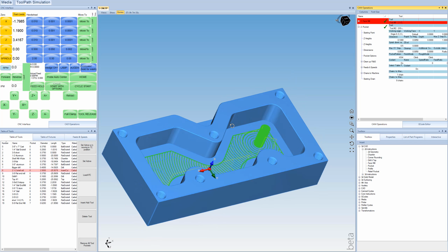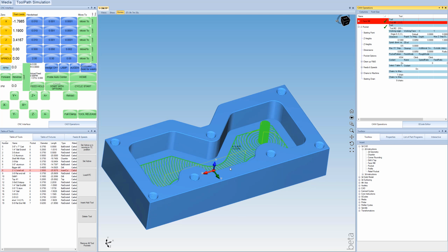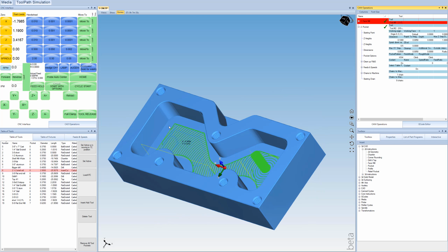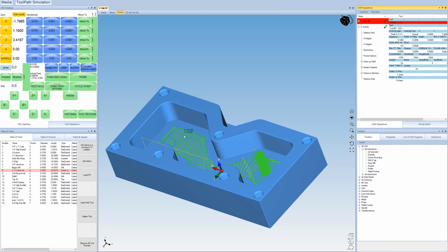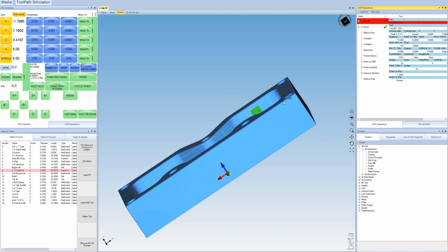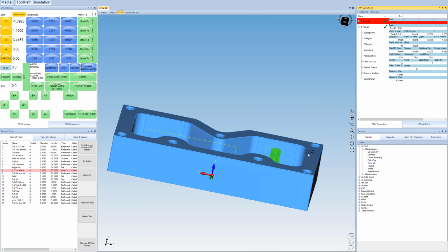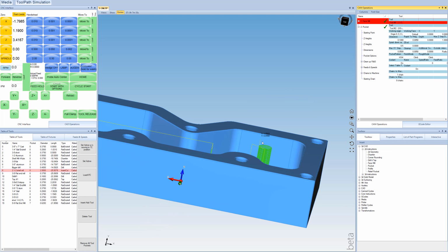And one thing that's really great here is we don't have to insert our depths or have any dimensions, because all that information is contained in the step file, right? So we basically just select the face we want to cut down to, and it understands the adjacent face where it would start from, so up here, and it starts to spiral in from that location. Yeah, so it's a big benefit to work with 3D models.